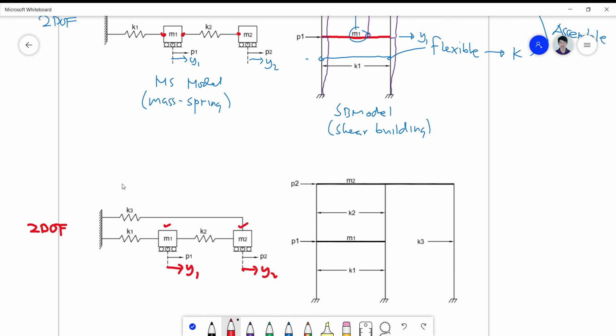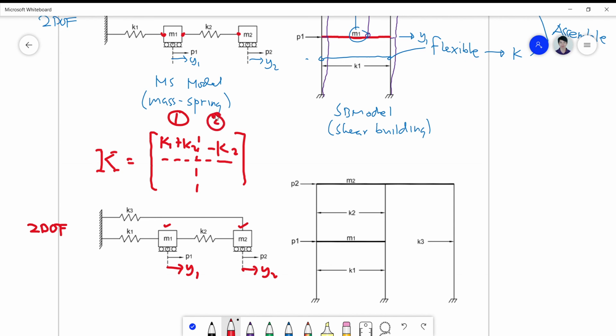Okay, and how do you define now your structure stiffness K on the basis of connectivity alone? So we simply again do ocular observation on Y1. So this is a 1, 1. Connected is K1 and K2. And for 1, 2, okay, so this is now 1, 2. Connected is K2. It's negative. Okay, remember this is the column number 2 there, and the row number is 1 here.